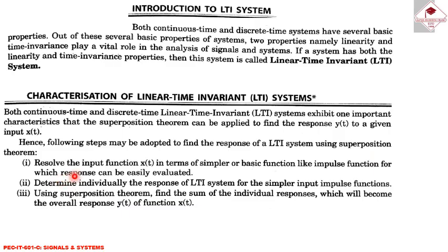Number 1, resolve the input function x(t) in terms of simpler or basic functions like the impulse function, for which the response can be easily evaluated. Number 2, determine individually the response of the LTI system for simple input impulse functions. Number 3, using the superposition theorem, find the sum of the individual responses, which will become the overall response for the function x(t).